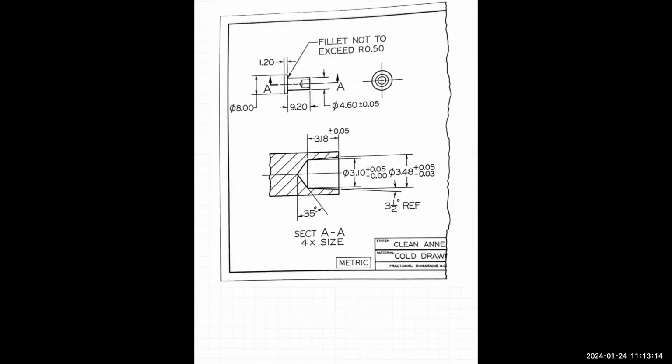Here's another cut. This is just a partial section, just going to show a certain part. A full section goes fully through the object, right? And then there are all these partial cuts that we can do. This actually looks like it's going fully through the object. This is the little object right here, some kind of rivet or something. And here's the cut, AA, right? Thickest line, kind of the thickest line on the drawing, that's good.